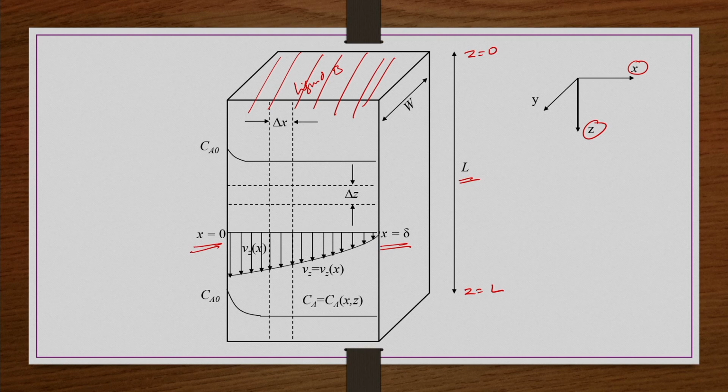So, why is that limitation given? When the gas is only slightly soluble, or penetrates only a small thickness, you can say that the viscosity of the liquid film is not affected. So, the velocity distribution within the film will not be affected. This understanding is important. Once you have this understanding, problem solving is very simple.